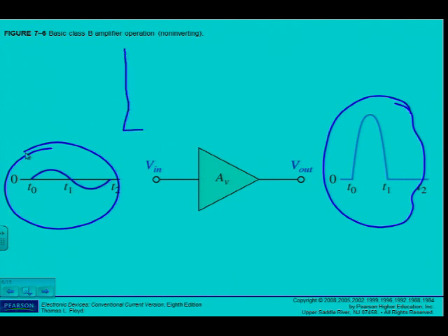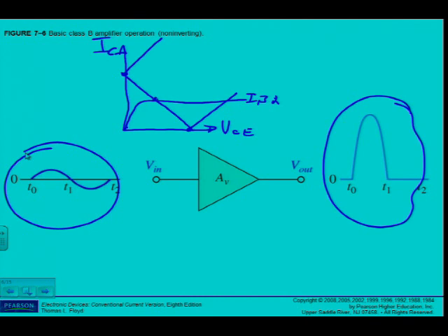Let's go back to our characteristic curve of the transistor, of IC against VCE, where I got my saturation points and cutoff points connected to the load line. I know for linear operation, I have to work between cutoff and saturation points. For class A, remember the Q point was determined by IBQ, VB, IBQ. That gave me my Q point for a class A amplifier.